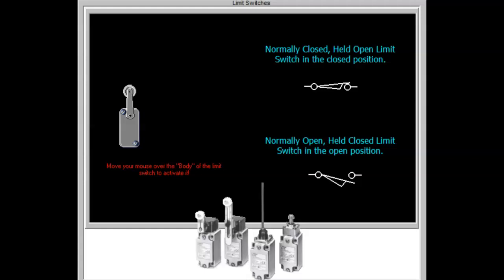Limit switches may be used as normal operating devices, or they may be used as emergency switches to prevent the improper operation of a machine or process. They may have momentary contacts, spring returned, or maintained contacts. The contact symbols shown here are the NEMA symbols for normally open and normally closed limit switch contacts.